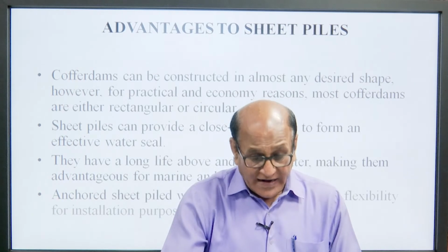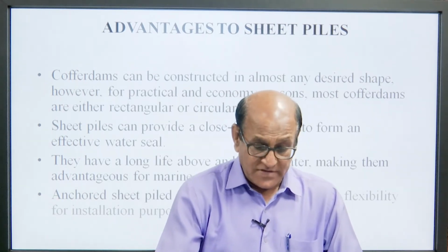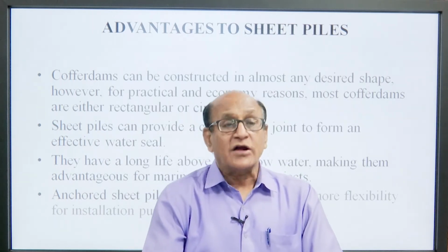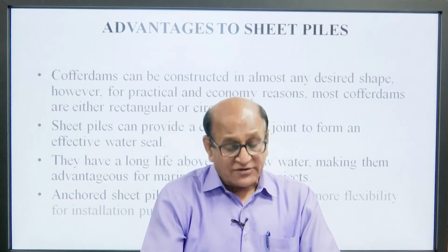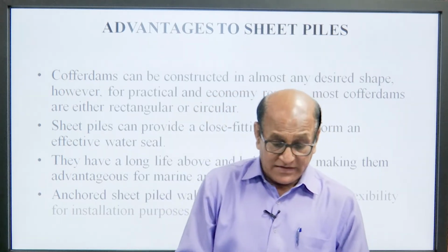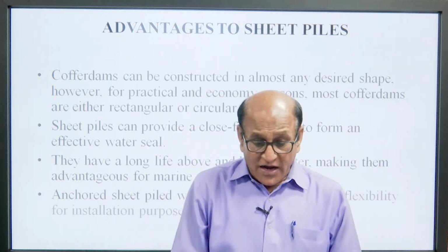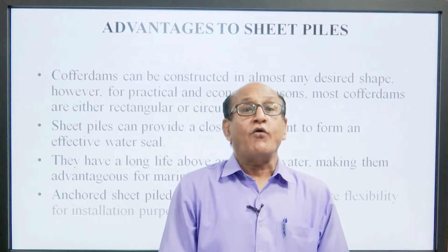Cofferdams can be constructed in almost any desired shape. However, for practical and economic reasons, most cofferdams are either rectangular or circular. Sheet piles can provide close fitting joints to form an effective water seal.